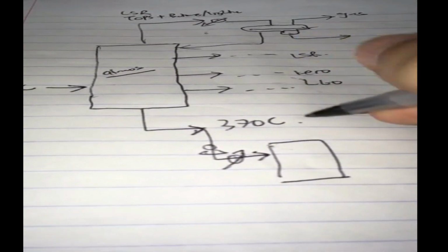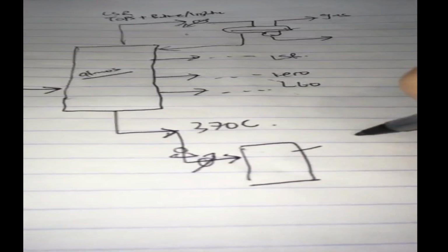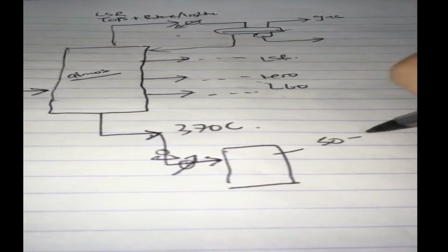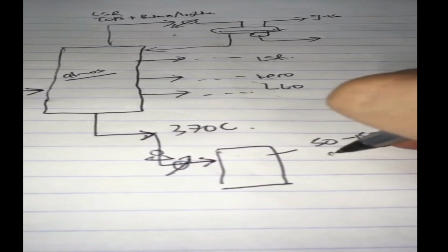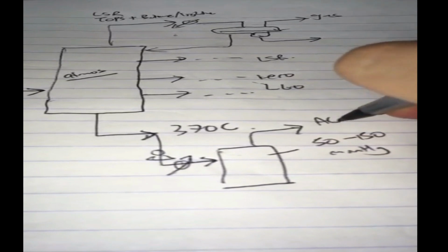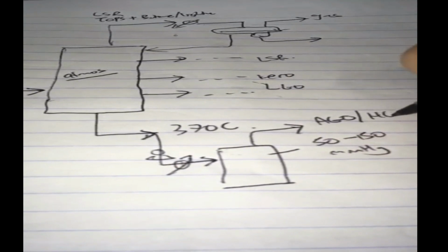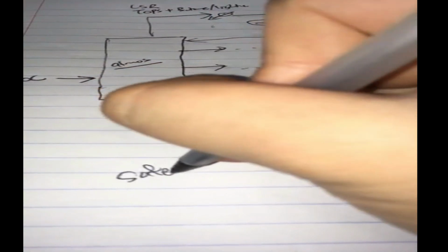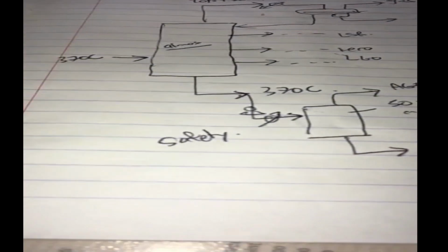If we want to make sure we have a safety barrier, we can operate another tower, maybe at a reduced pressure, to draw off our atmospheric gas oil and heavy gas oil. Here we have our long residue. Now this is the version with the safety barrier, right?